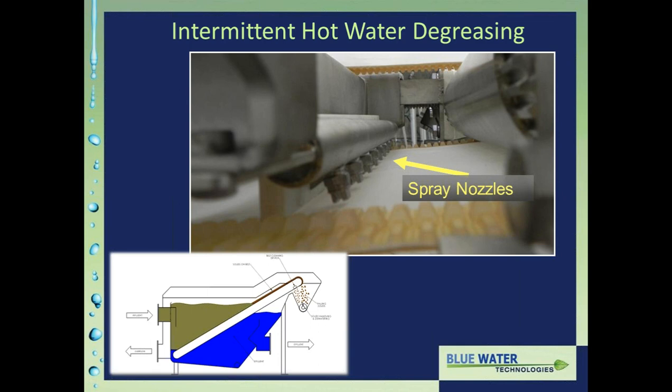We have these installed not only in stormwater applications, but also in municipal plants where there's a lot of restaurant grease that comes down the line, as well as scenarios like meat packaging plants, which are conventionally very high, or traditionally very high, in FOG, fats, oils, and greases. And these cleaning mechanisms are very well designed, and again, there's options for each of those scenarios to make sure that the client, the end user, has the most effective system possible.